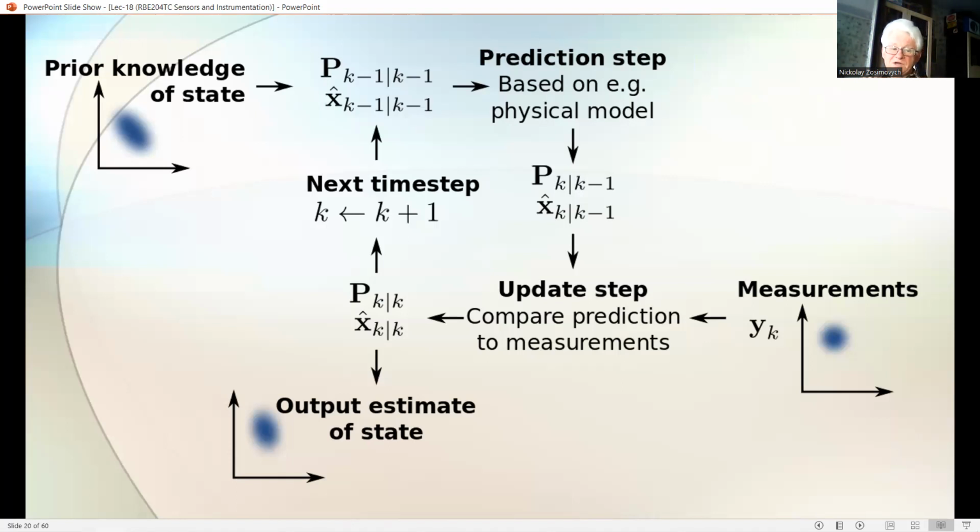As we will see, the Kalman filter uses a predictor-corrector method where a model of the process is used to first predict the estimated quantity and its error covariance, and then correct these two quantities by using the actual measured data.